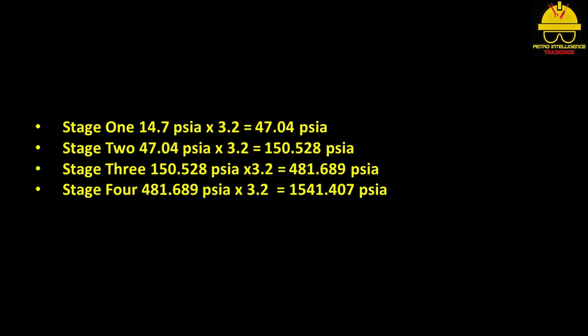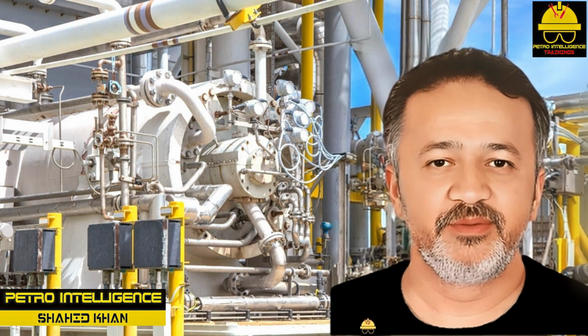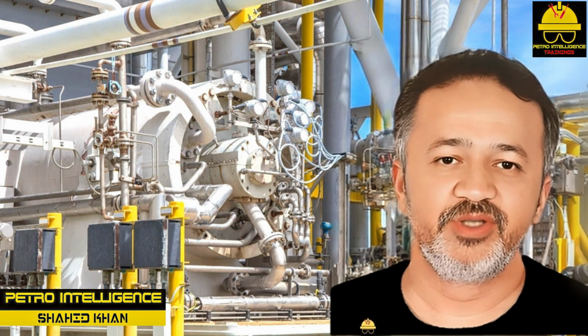The simple calculation used to calculate the pressure increase on each stage is: Stage 1, 14.7 psia x 3.2 is equal to 47.04 psia. Stage 2, 47.04 psia x 3.2 is equal to 150.528 psia. Stage 3, 150.528 psia x 3.2 is equal to 481.689 psia. Stage 4, 481.689 psia x 3.2 is equal to 1541.407 psia. The basic components of a centrifugal compressor are shown in the picture.